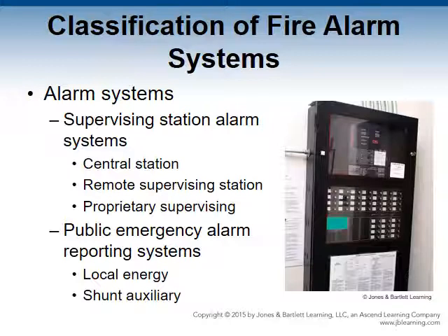The most common is a system that uses a digital alarm communicator transmitter, known as DACT, at the premises, and a digital alarm communicator receiver, abbreviated as DACR. Once a fire alarm system activates, a fire, trouble, or supervisory signal is sent to the DACT panel, which then transmits the signal to the central station facility via an approved transmission medium. Two methods of transmission are required to ensure redundancy and backup protection. Once the central station receives a signal, the station personnel take appropriate action.